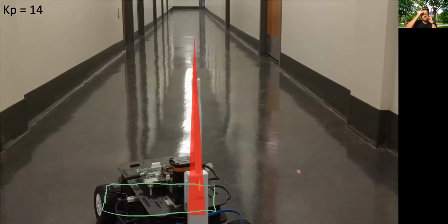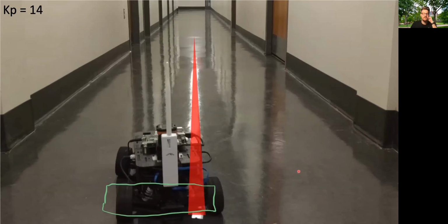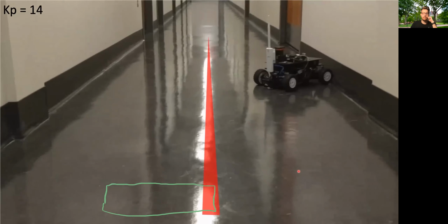Now here is a small video for you where you can see where we set up such a proportional control. What we see here, we will overshoot with this algorithm very easily. The car will oscillate around this center line, or the center line we try to follow, really easily in that way, which means we need to tune this parameter first of all so it works out better.